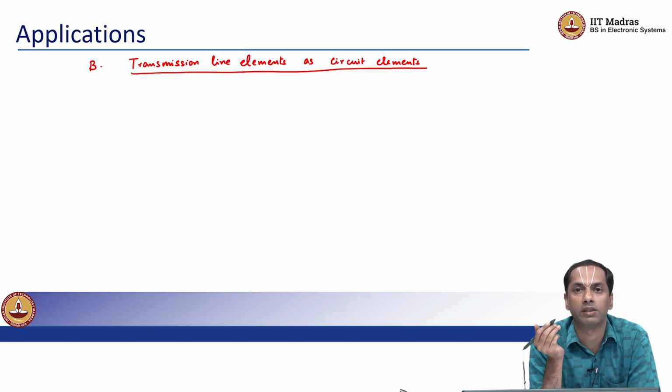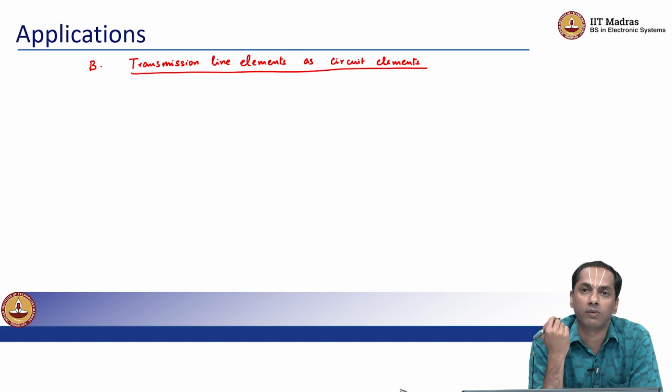So at high frequencies, we noticed that a capacitor doesn't seem to act like a capacitor but more like an inductor, right? Which means that our traditional notions of building ideal circuit elements like capacitors and inductors have their own drawbacks. In that specific example in the mystery problem, I said this was attributed to the leads, the long leads of the capacitor.